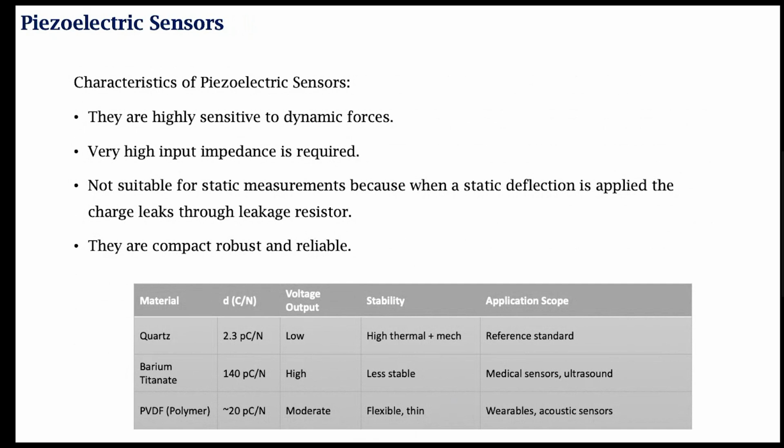Quite often, piezoelectric sensors are used as intracochlear pressure microphones. This material, usually PVDF, really small PVDF discs are used to sense nano level changes in the perilymph material for cochlear prosthesis. That's another application. Frequently, they are also used in MEMS accelerometers, for example, to measure vibrations with a relatively high sensitivity or relatively high reliability.